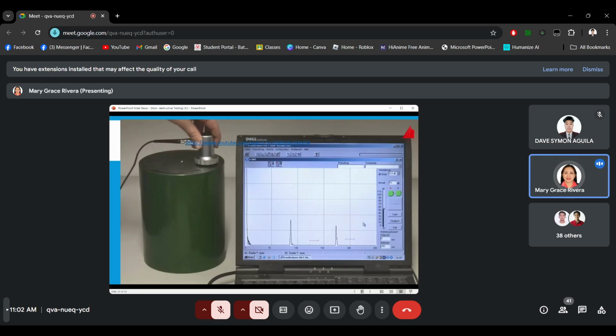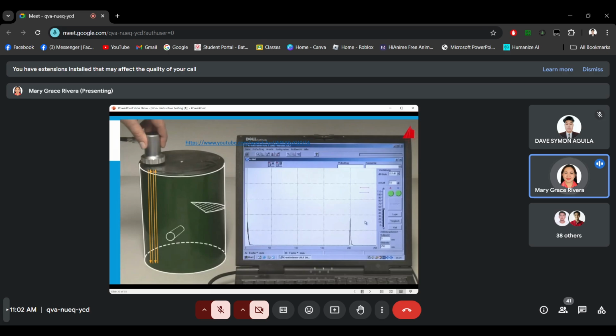Another echo indicates a defect in a depth of 87 millimeters. The second smaller echo at 174 millimeters is caused by double reflection on the same imperfection. And these are the defects: a drill hole and a saw cut. Filled up near the surface and painted, they are not visible from the outside.